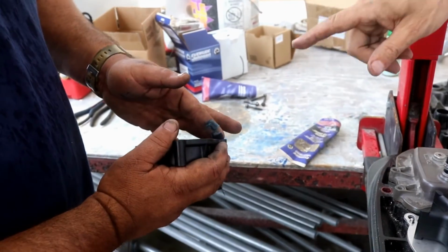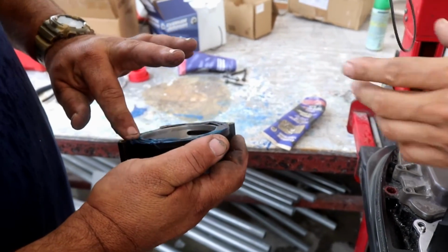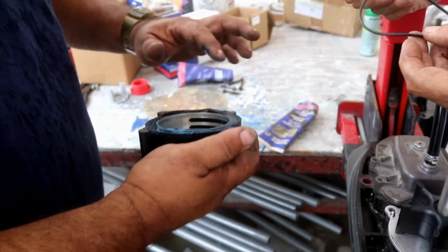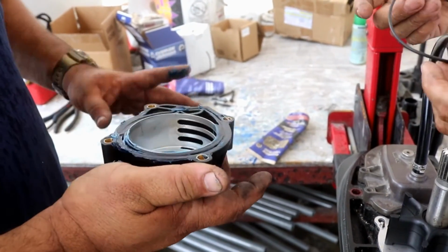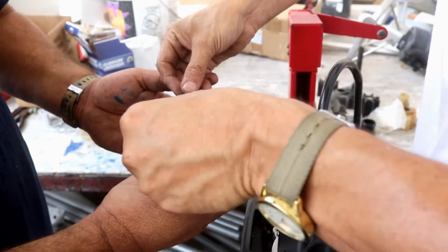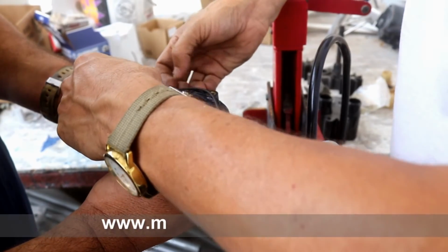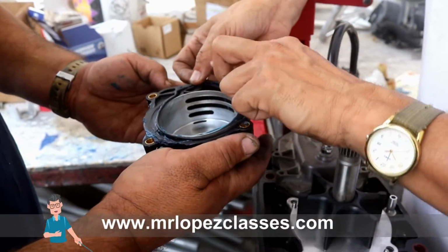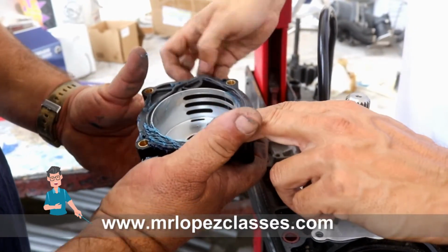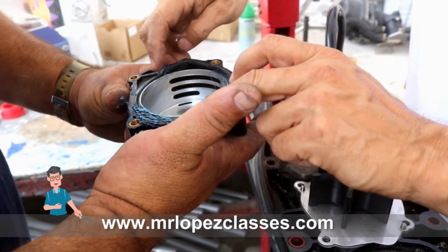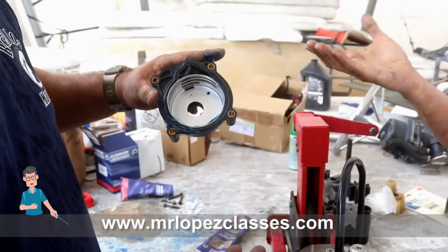And now you apply grease on the O-ring. Okay, perfect. In order to hold the ring, no, Danny? Yes, so it doesn't fall. Because what happens is if it falls, you risk the chance of pinching the O-ring. Yeah, that's true. All right, and now we are ready to locate the O-ring in place. Right. And because you have the grease, nothing falls out. That's perfect.